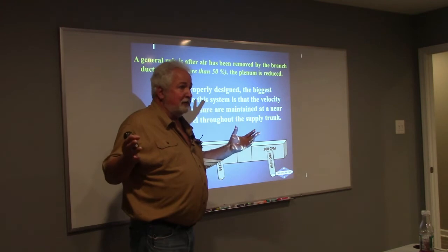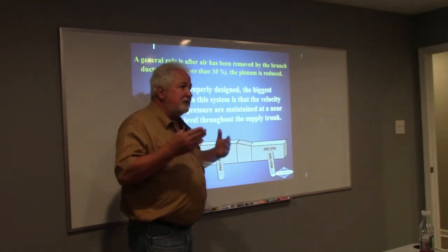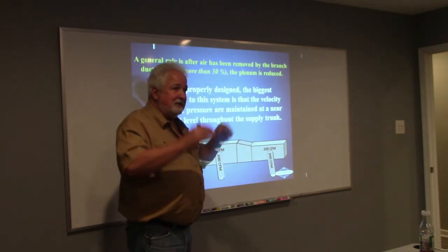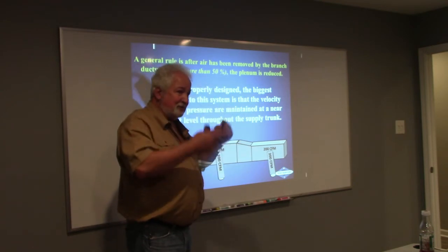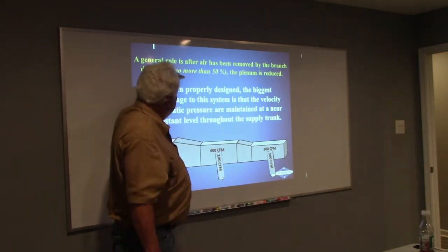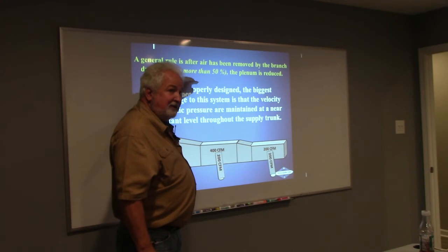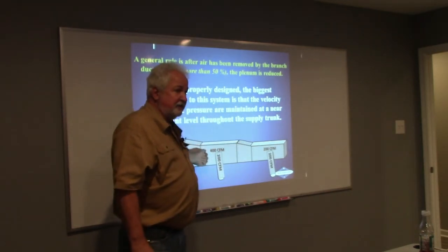Well, I don't know what 50% of the velocity is until I started measuring it. But then I started figuring out that if I have 1 square foot, velocity and CFM are exactly the same. One's directly proportional to the other one. So I turned it around and said that if you reduce 50% of the airflow, the CFM, that's when you're going to transition.